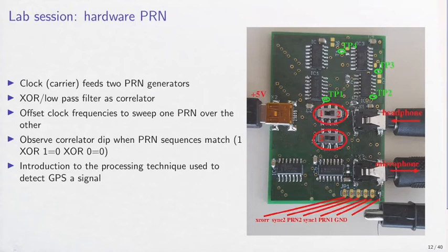For the second part of the lab session, we will address how to disseminate this pseudorandom sequence. So far we've generated the spectrum spreading signal by using a noise source, and a noise source cannot be shared between multiple users. So we need a way of identifying what the random sequence is, so that a user can generate this sequence locally and have the fine timing capability. So this is what Gold codes are.